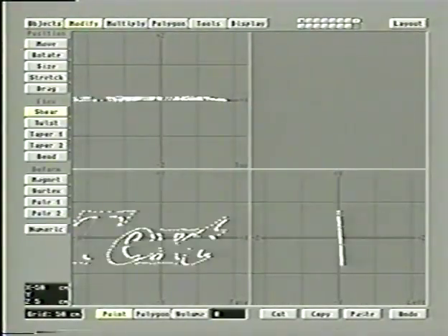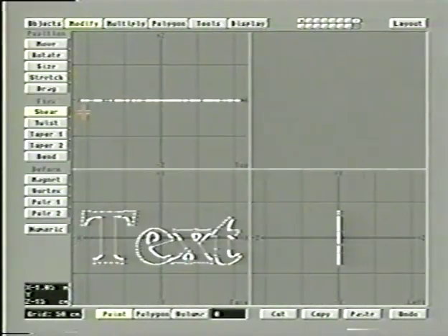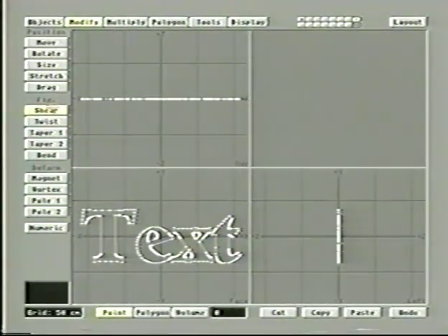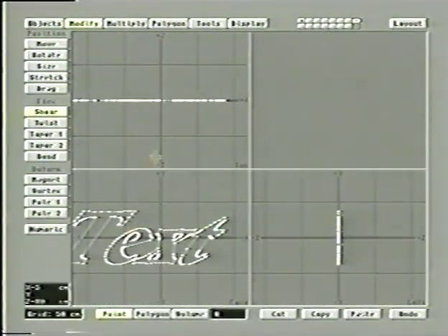The thing that's dangerous is sometimes you can get it right where you want it, but it's tricky, it's a little bit off angle. Well, there's a quick way I can fix that. If I undo my setting and then go to the numeric option for that flex there, I can see that my offset on X is negative 0.55, and my offset on Z is 0.05. Well, I don't want any offset on Z, so I'll just manually enter 0, right? Then hit apply, and you notice now it moves it in the X direction, but nothing in the Z direction.